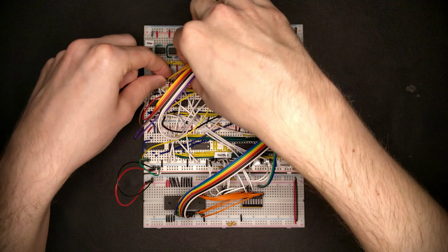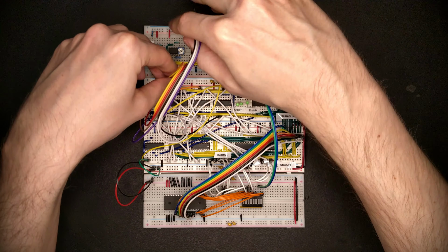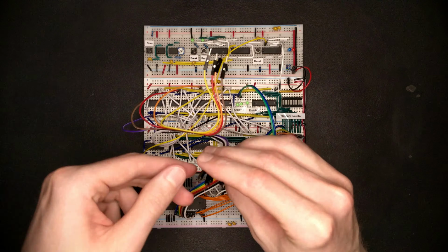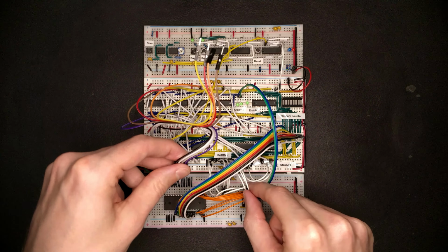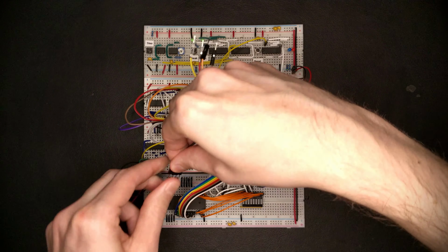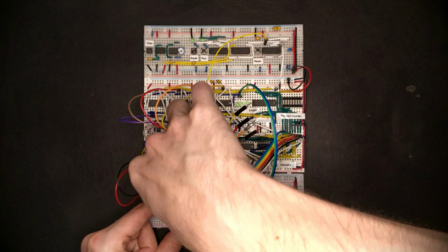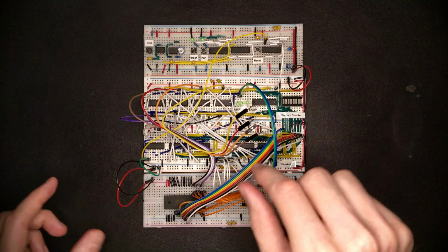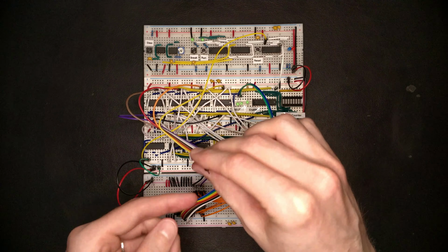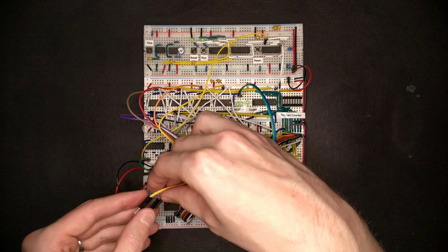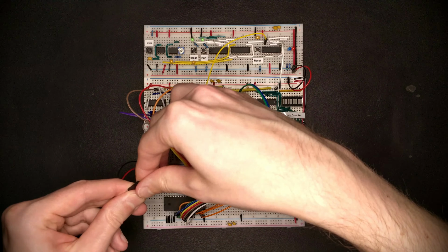And then we also want to be able to control what the absolute jump address currently is. Let me bring the lower 4 bits down to our memory module, basically the same way we connected the relative jump offset over here. Now, in the case of the absolute jump address, we want to connect the upper bits that we're not using to 0 because we're not doing any addition on it. So there's no real sense in doing a sign extension here.